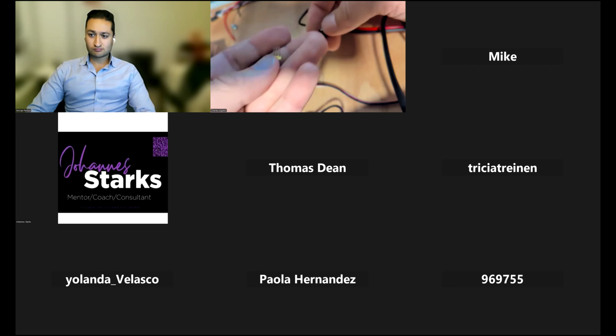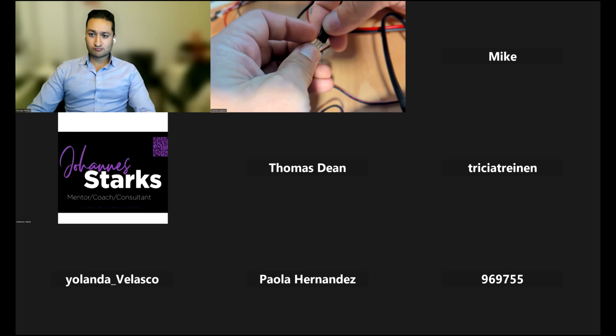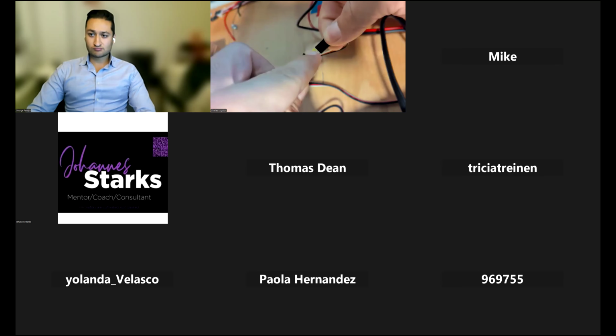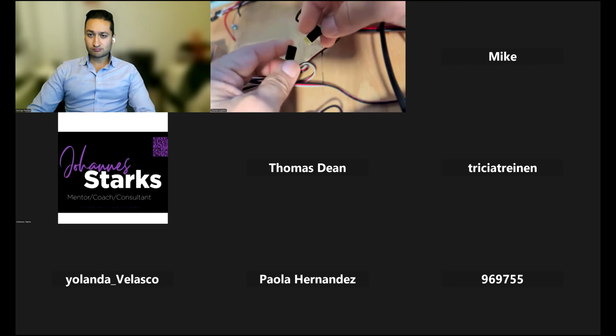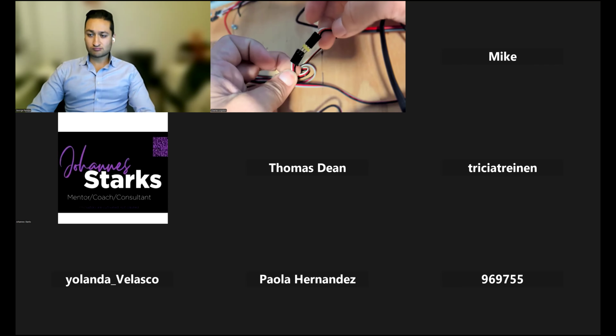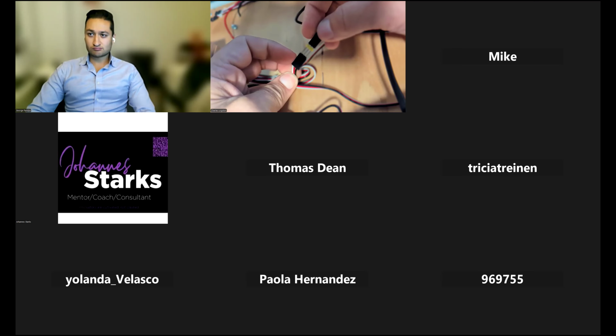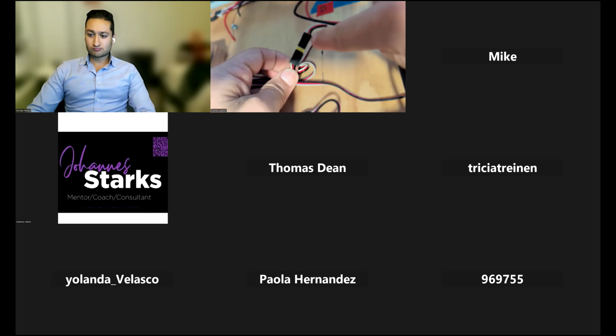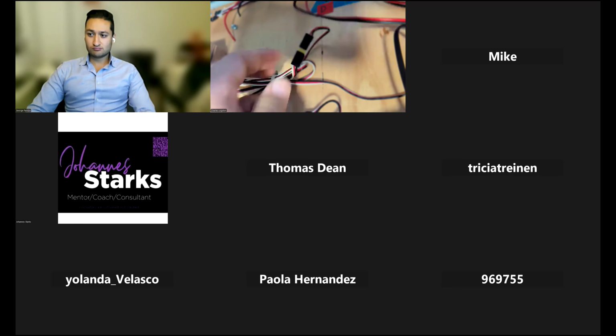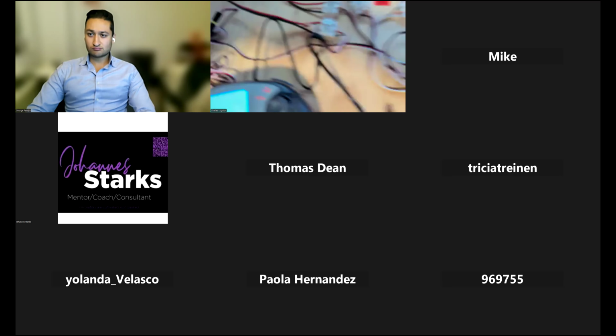So we have these header pins, and in the 2025 season, it was recommended that these get super glued to the servo so that this just becomes a male connector instead. That way you don't have to worry about losing that header pin. But when you're lining them up and plugging them into a servo extension cable, make sure you line the white wire up with the white wire and red wire up with the red wire. Otherwise, the servo just won't move. So that's talking through the basic hardware setup of moving the servo.